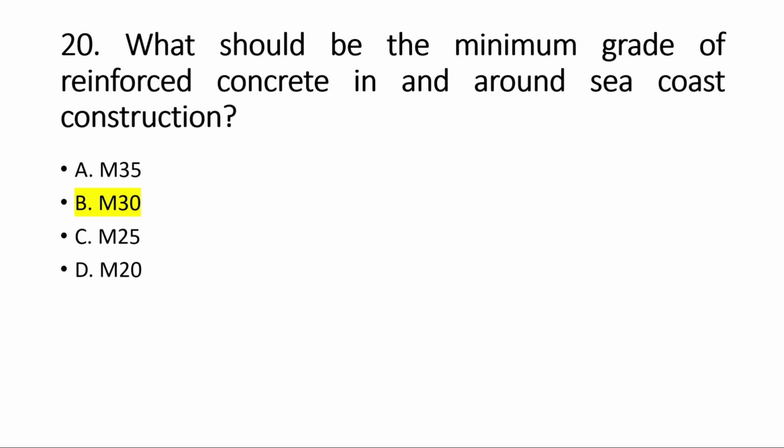So here you can refer, your answer will be M30 as the minimum grade if you are having construction around the sea coast. Okay, so we know that the use of slag or pozzolana cement is advantageous under such conditions, under this severe condition. So option B is correct here, M30.